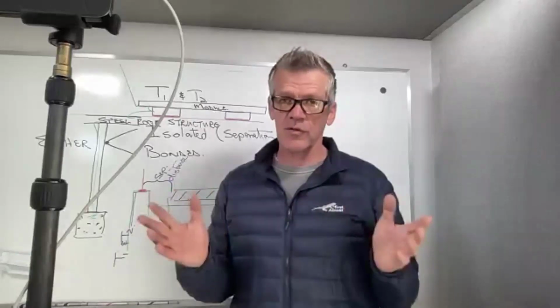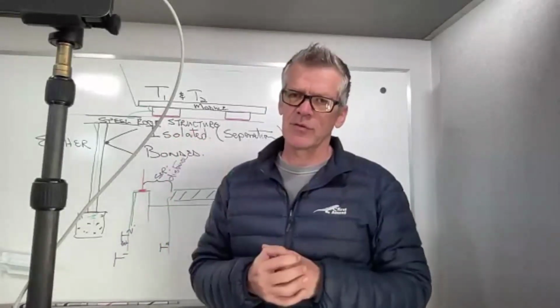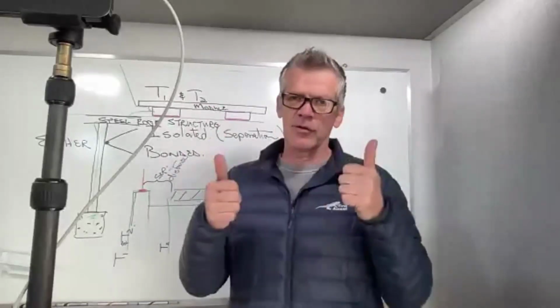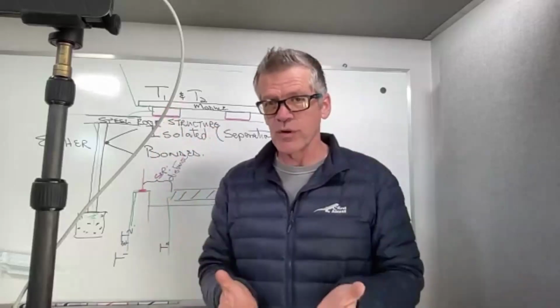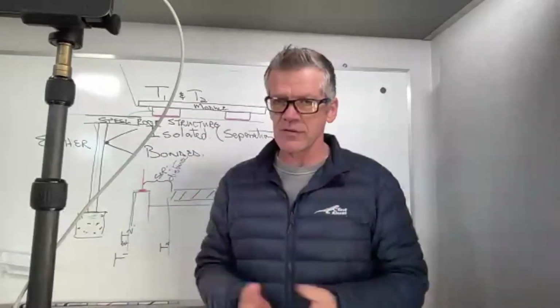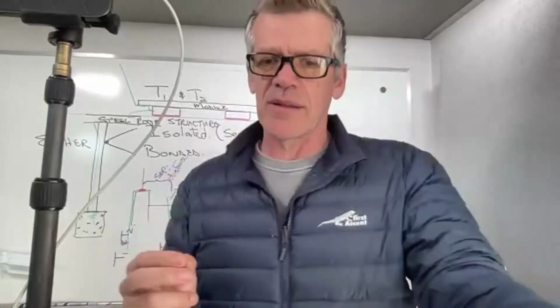If you look at the social media WhatsApp groups, as long as you have a 16 millimeter squared cable and an earth spike, you're sorted. As far as how it works in practice, that is not going to be adequate if you are expecting a direct lightning strike. Kenneth, do you have anything to add there?